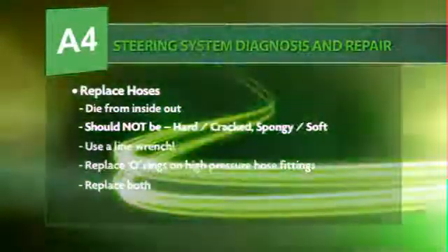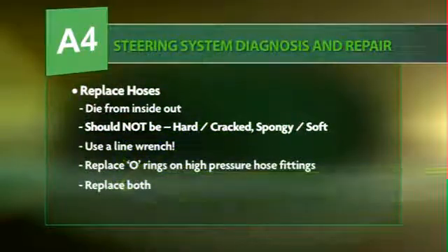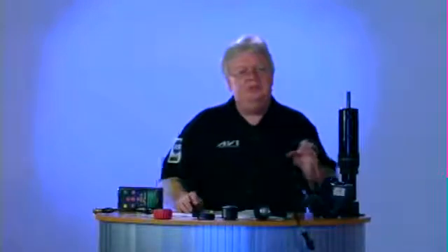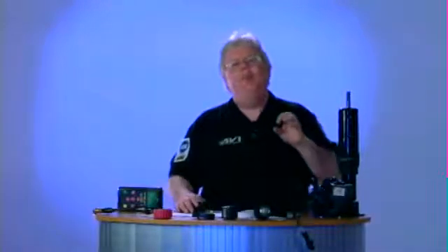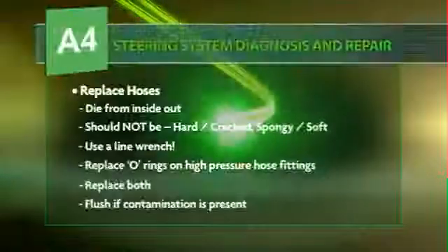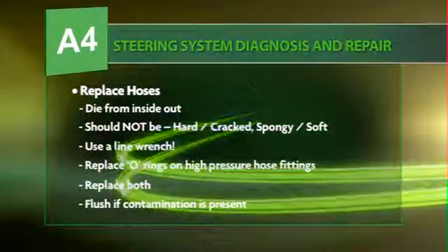So replace both the hoses when you replace a power steering hose, not just the pressure or the return, replace them both, because if you've got that murky black stuff from the hose dying from the inside out on one, it's going to be in the other. And then flush if the contamination is present anywhere.